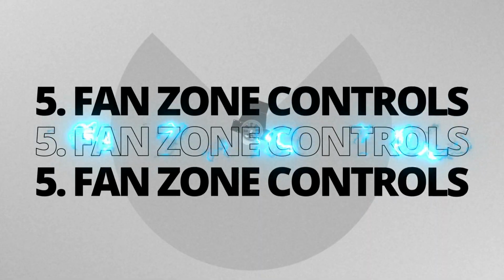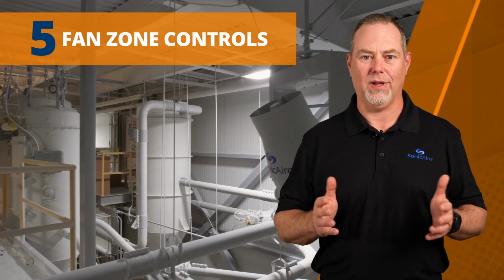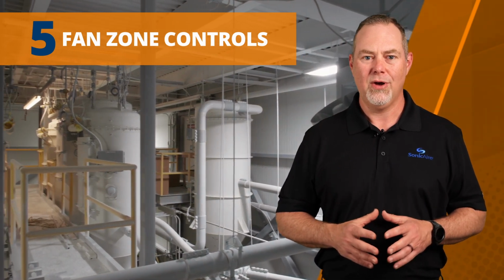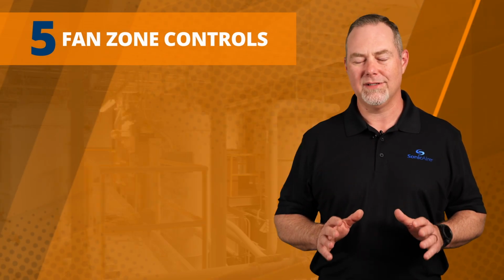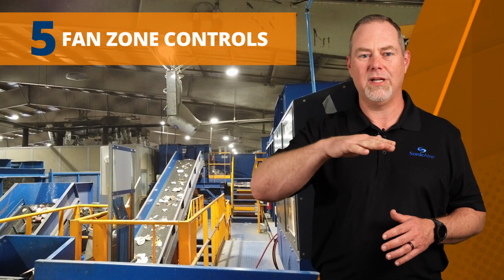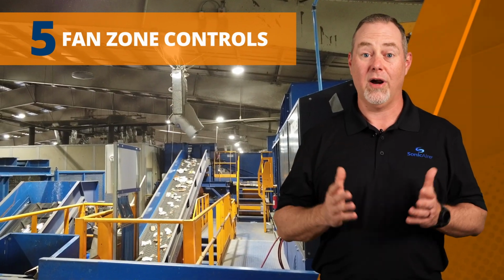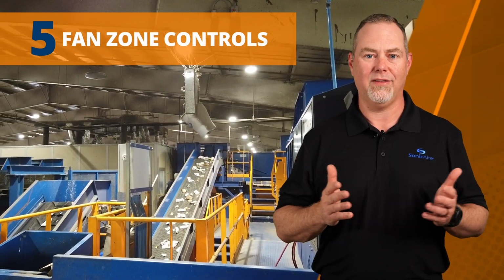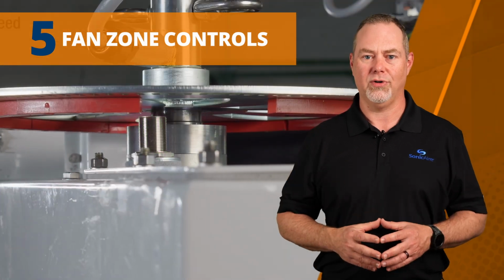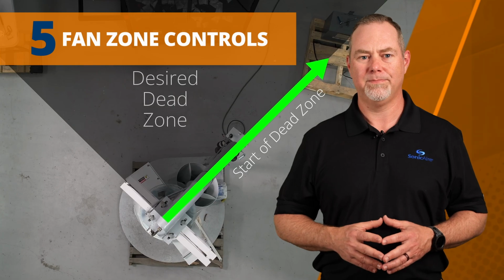And finally, do you have any sensitive processes that would be disturbed if a strong blast of air were to blow on them? Well, if anything comes to mind, please let your sales rep know. If these processes are below where the fans will be installed, that's no problem. We can fine-tune the fans for that. However, if it's an area to the side of the fan, we'll need to install one of our zone control kits on the fan to prevent it from blowing into unwanted areas.